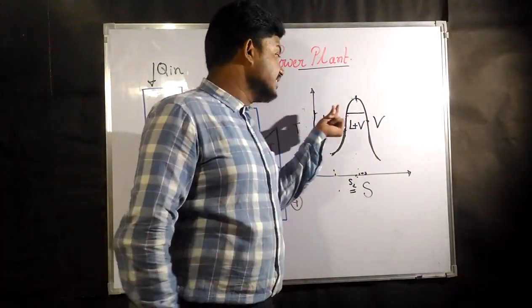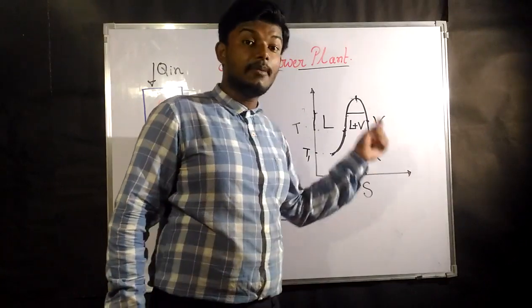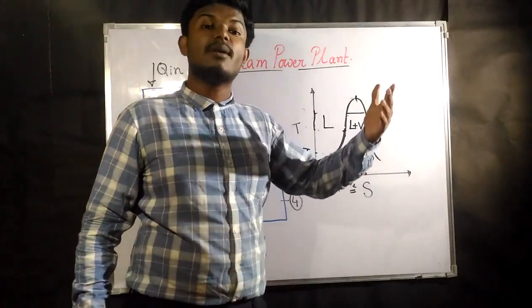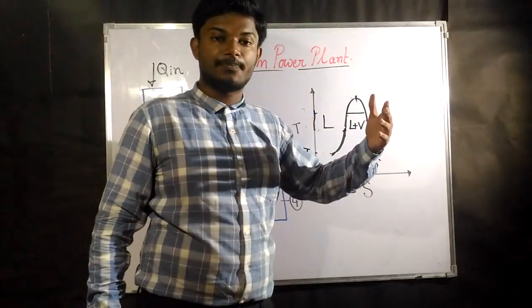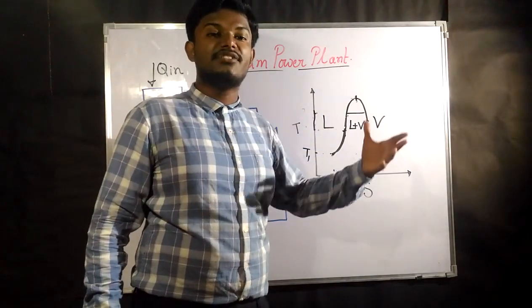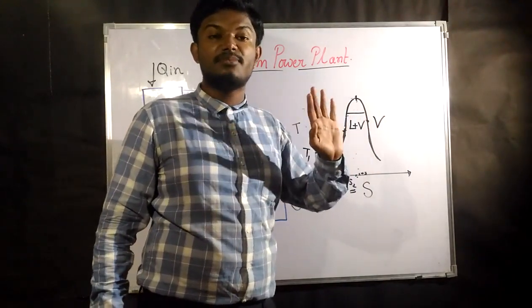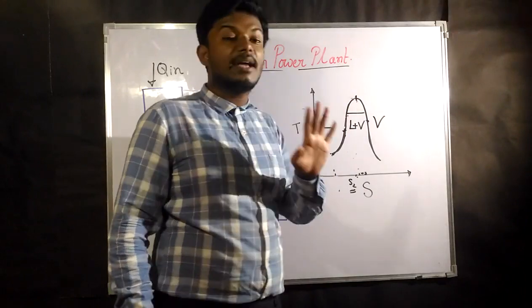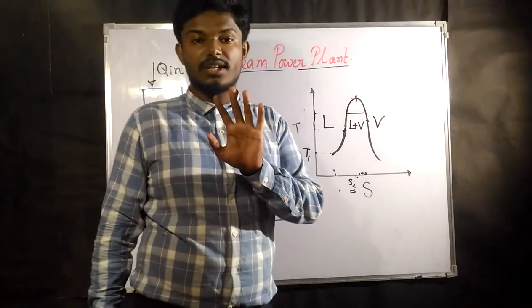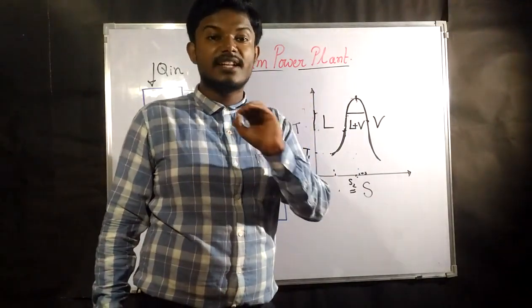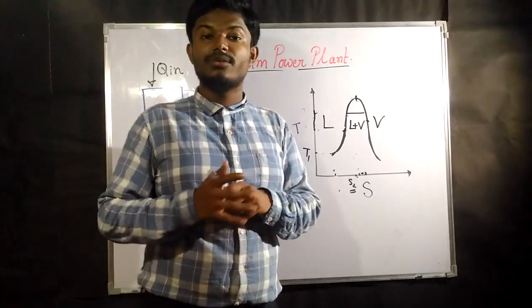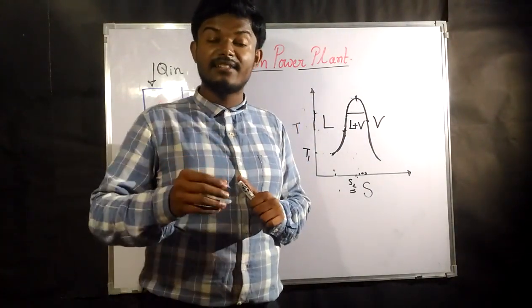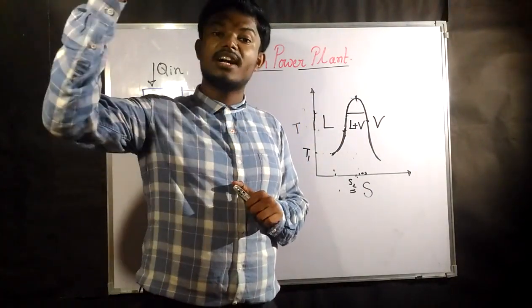That means in that line the entropy is increasing, but the substance is evaporating or changing its phase. Okay, the substance is changing its phase, and changing its phase means what? Inside this the temperature is always going to be constant. The phase changing temperature is always constant. You all know that. While you boil, the temperature, until and unless every bit of the water has been converted to